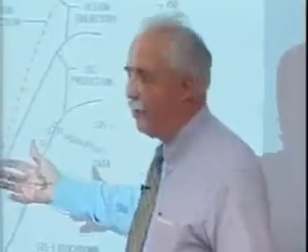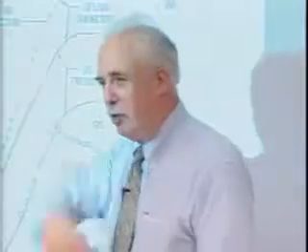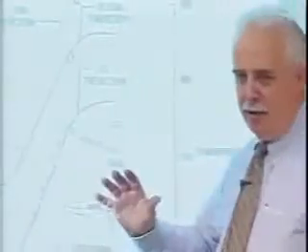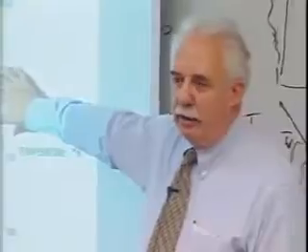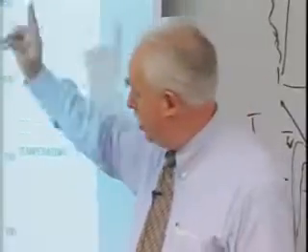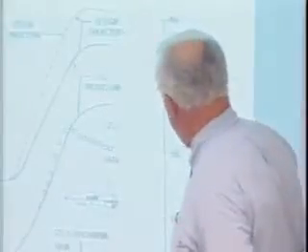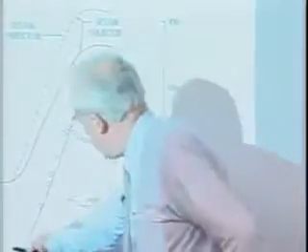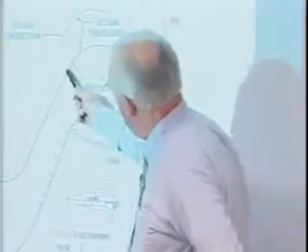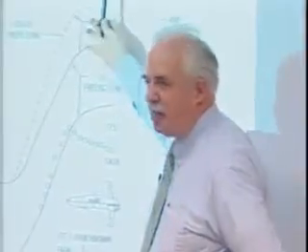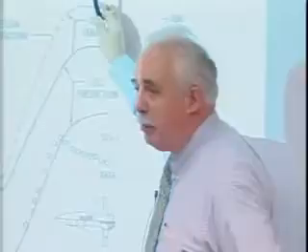If you read the TPS section in that report, you say, those guys with the heating, they're just way too high. Right here, we were right on, okay? So this is a purely TPS test, except for, it turns out it was my fault here. In any event, here comes the data along. This is the prediction for this particular flight, STS-1. Right here, this is what we predicted for STS-1, this is what we would have predicted for design, and this is the design technology prediction, which has a little conservatism in it, obviously, and on purpose.